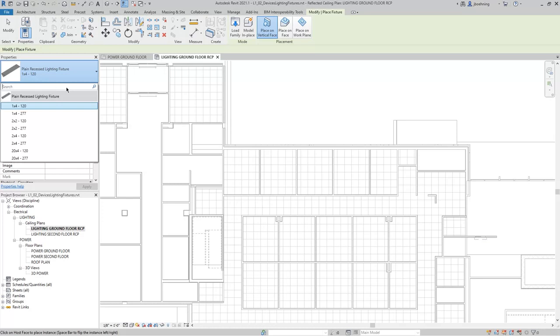Just to see what I mean by that, if I type lighting, you can see lighting highlight in the family name. And then if I type a space and then enter 2, all the 2's highlight. You'll notice that lighting space 2 does not appear in the same text string in the family name or the type name, but each of those individually is highlighted. So if I'm searching for a lighting 2x4, some type of 2x4 lighting device, those will highlight in either the family name or the type name.